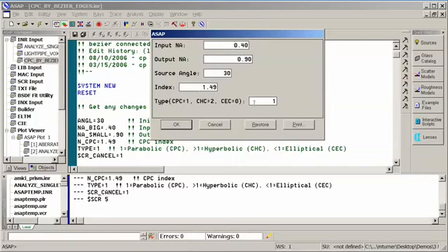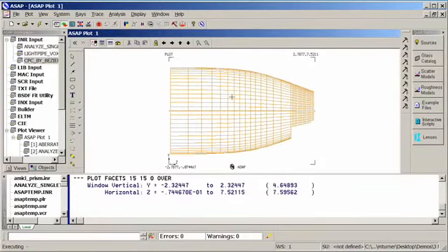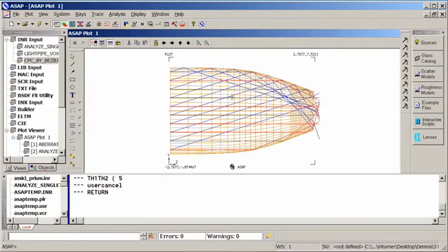So what I'm going to do is let ASAP design for me a simple compound hyperbolic concentrator. I'm just going to change this data entry and then click on OK. Now ASAP has defined the geometry for my concentrator, and we can launch rays through the system. We can vary the angle of input, and we can do analysis at the output plane to determine what the efficiency is and any other information we might need about this particular concentrator, or we can use this concentrator as the input or output to any other optical system.